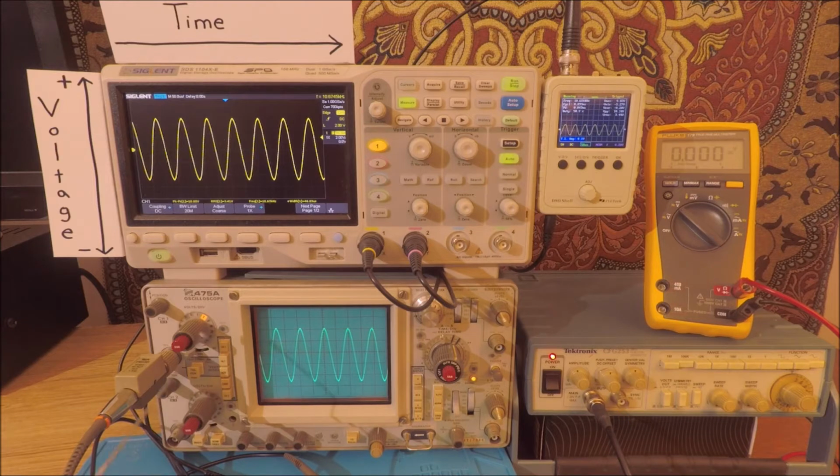On the analog scope on the bottom, that's this control right here. In fact, it's labeled volts per division. It's currently set at 2 volts per division. If we look at the sampled signal here, we can clearly see that it's deflecting up and down, and there's a grid across the screen. So currently at 2 volts per division, we can measure the deflection of that signal. This exact signal is going plus and minus 5 volts, so in total, we have a 10 volt peak to peak signal.